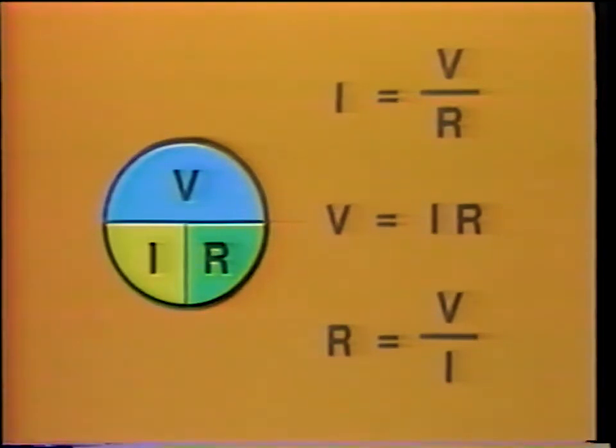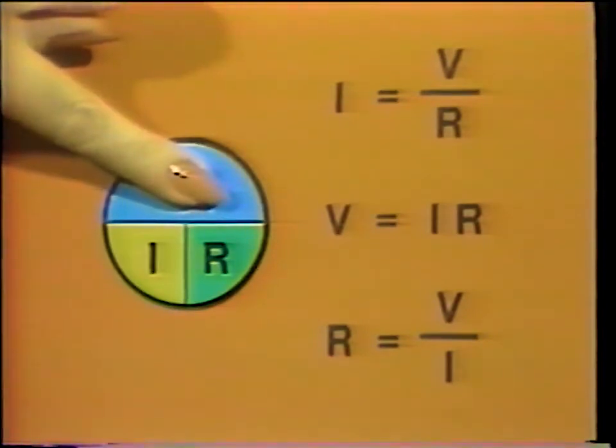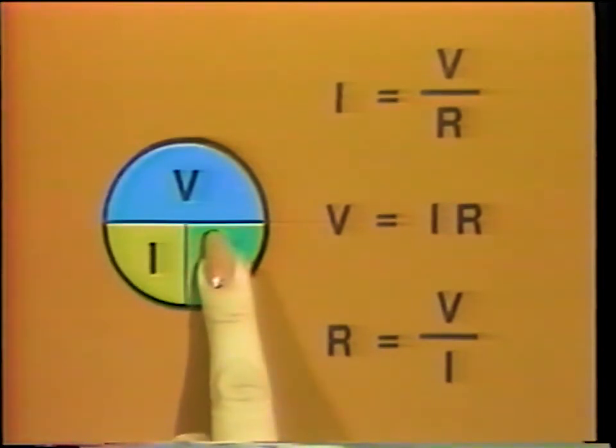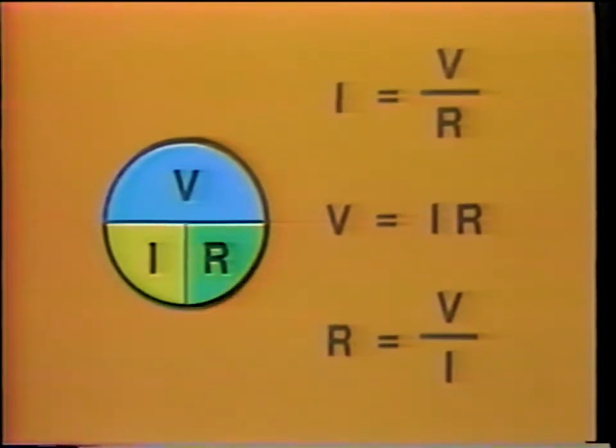We can easily remember Ohm's law from this diagram. Just cover up the term you want to find, then V equals, I equals and R equals. In this circuit, we've been discussing direct current, or DC. In DC circuits, current flows in one direction only.